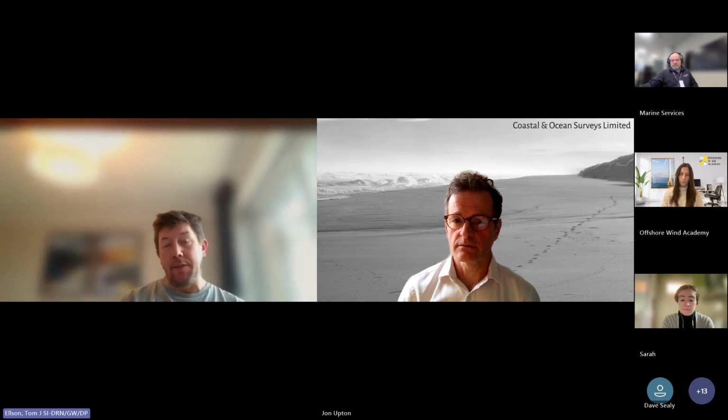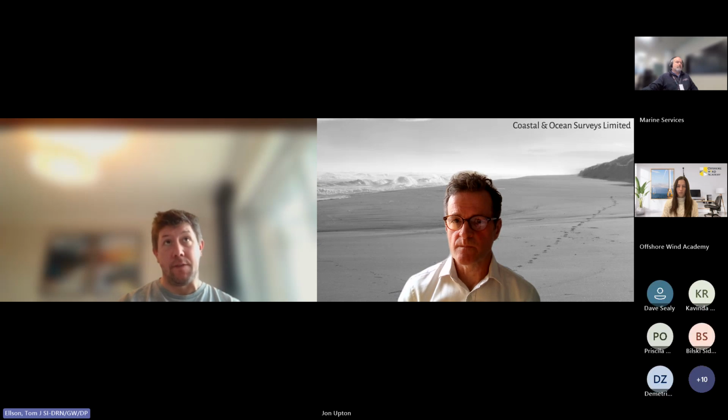And you've mentioned buoys already. I think Sarah also mentioned buoys in the execution phase. So we would expect typically to have at least 1 or 2 Metocean buoys in the construction phase of the wind farm, which are doing live measurements of sea state. That coupled with a solid, robust forecast, all of which we get from third parties, means that your Marine Coordination Centre, who are basically the people who are monitoring all of the activities in the construction phase, have a really good view of the conditions that you're expecting on those days and into the future, 5 days into the future, so you can plan your activities and make sure that you're working in the right sort of agreed weather windows.